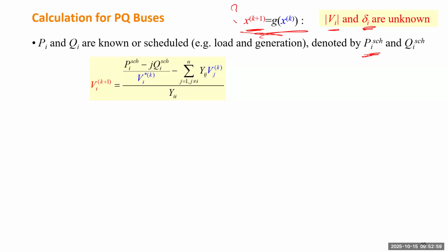Generation dispatch is just going to solve a more general power flow analysis problem, where you have some room to adjust between the lower limit and upper limit for each generation. So by that section, we'll be able to know the scheduled value for each generator. But in this section, in power flow analysis, we assume the P and Q are already known for the load.